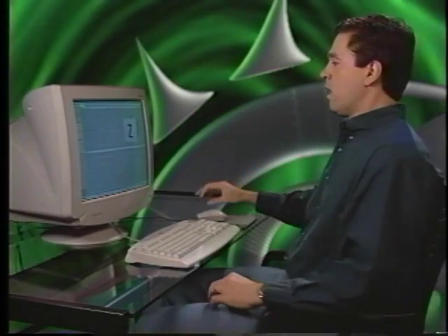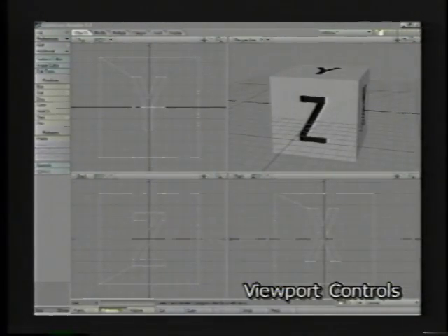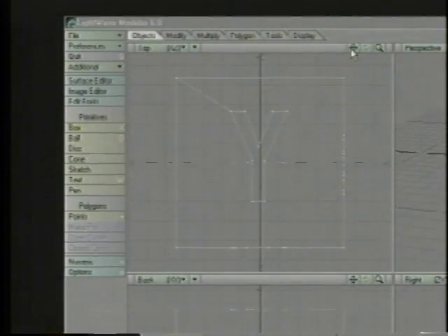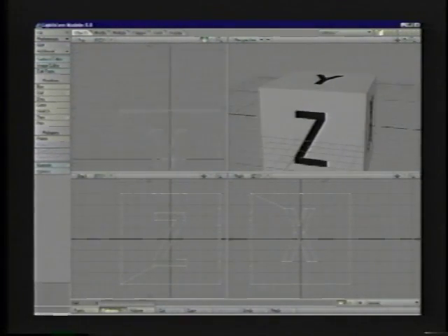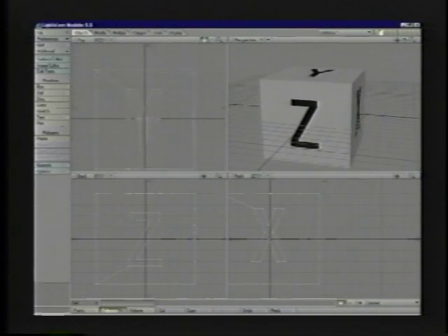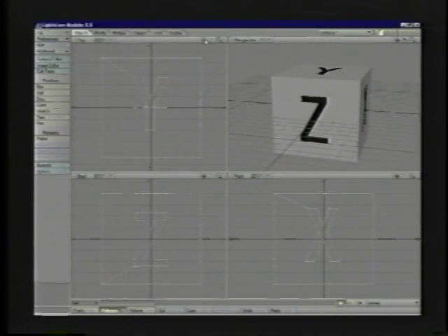So using x, y, and z, we're able to determine the position of a point anywhere in space. Okay. I should also mention just a couple other quick things that we can use on these menu bars here. We can pan our object around within the viewport by selecting the little pan icon up here, the little four-arrowed thing. Hold down the left mouse button and you see I can move that around within the viewport there. Now, I'm not actually moving the object in space. I'm just kind of moving where my virtual camera is when I look at it.